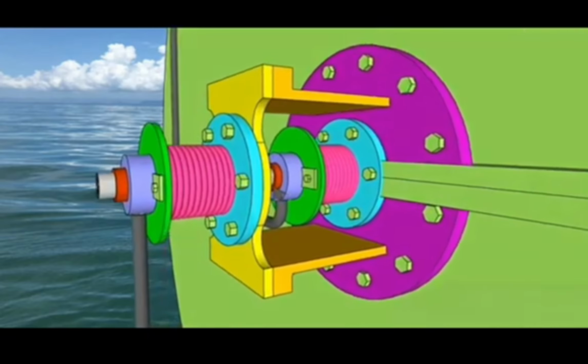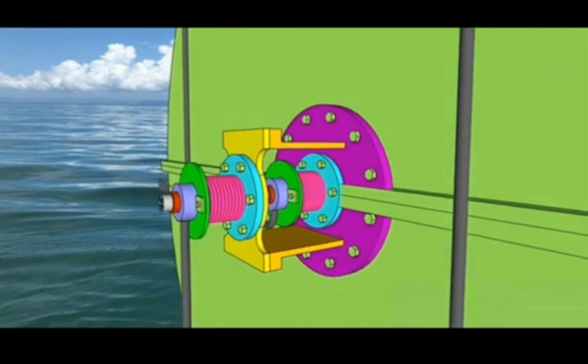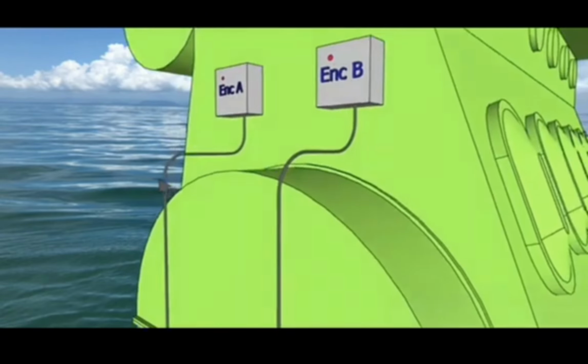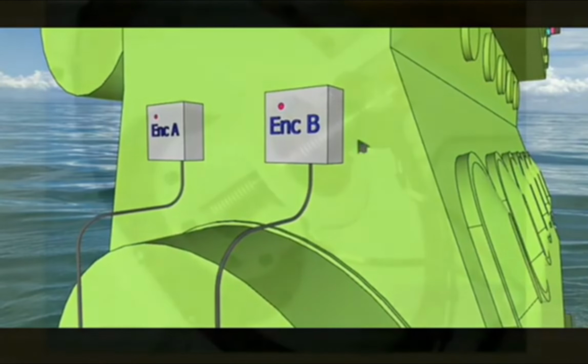The reference will be taken from number 1 TDC, and the second one is 45-degree offset from the number 1 TDC. They are fitted in that way, and in a few minutes I will explain why this offset is required. This is the setup they have given. And next, from this encoder the signals will go to the amplifiers, this encoder amplifier.